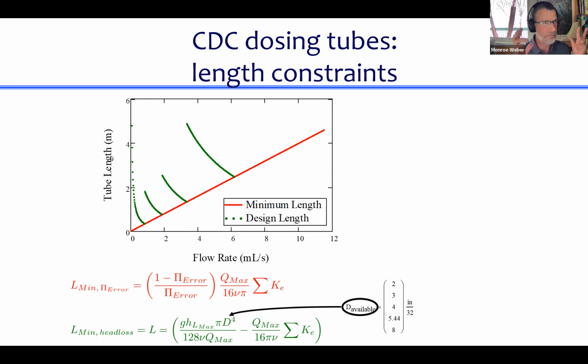So that's one reason not to make the head loss really large in the linear flow orifice meter. So then what's as small as it can be and still have it work nicely? I feel like this is kind of a human scale question. Like, it should be nice for an operator to read a number off the side of the entrance tank and know what the flow rate is.